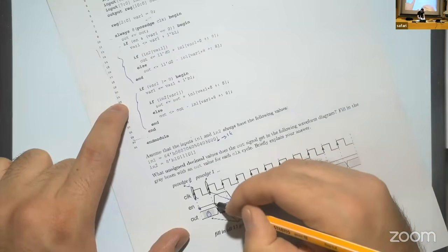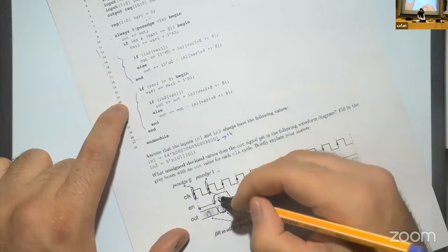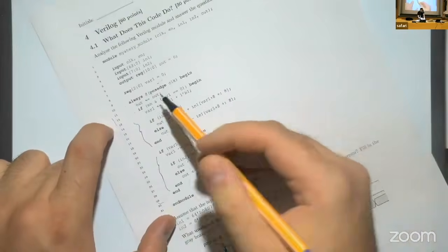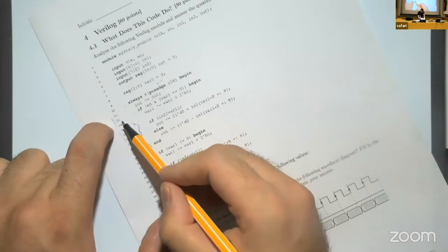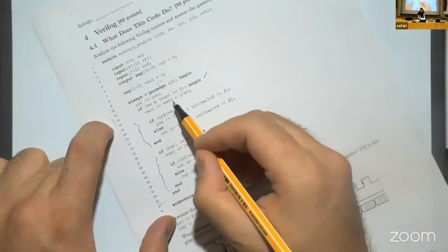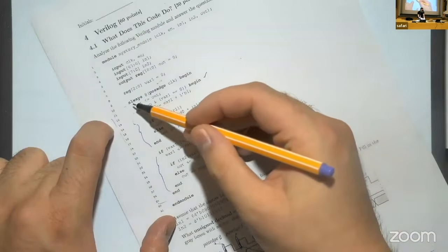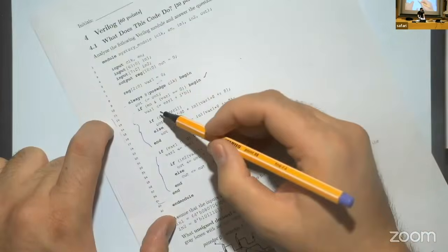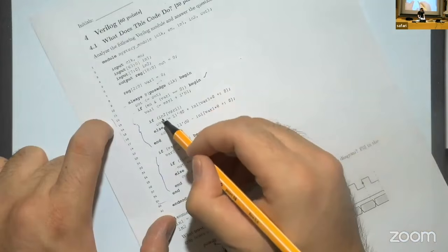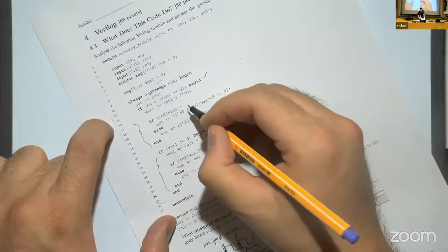Here we see that enable has risen. That means enable becomes 1. Now this if clause, which is in the 12th line, will be satisfied. That means variable 1 becomes 1, but it becomes 1 only after the always block is executed. So now it's still 0. Here we go into this if block, into variable 1, which means into the 0th bit.